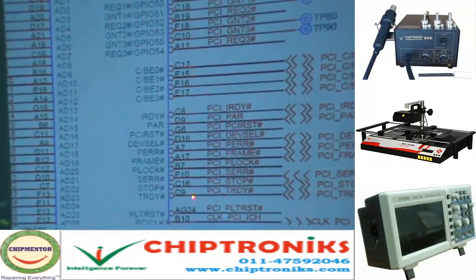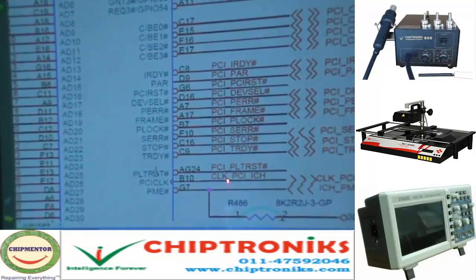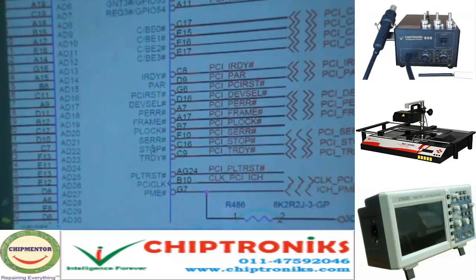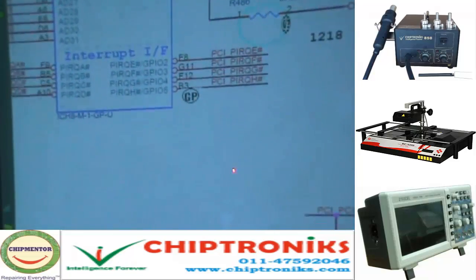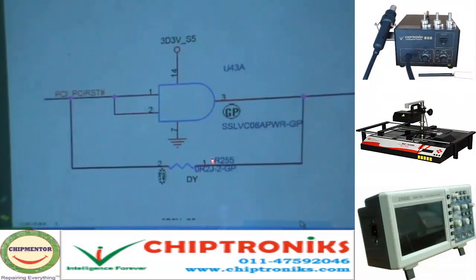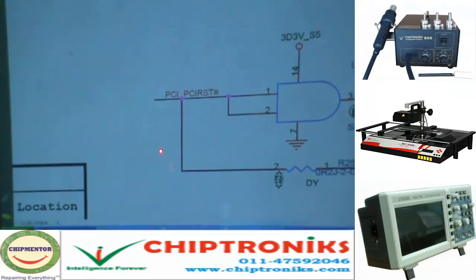These are the important signals. PLT reset. What is the full form of PLT reset? PLT reset is platform reset. You can measure 3.3 volt over here, just below this block diagram. There are two signals, PLT reset and PCI reset.